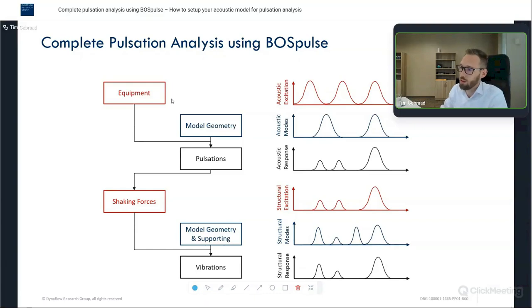can lead to pulsations. And these pulsations don't necessarily cause problems, but a result of these pulsations is that you're going to have pressure differences in your system. So you might have 2 elbows in your system where you have a pressure difference, and as a result, there will be an unbalanced force on that section between those 2 elbows. And that's what we call shaking forces.